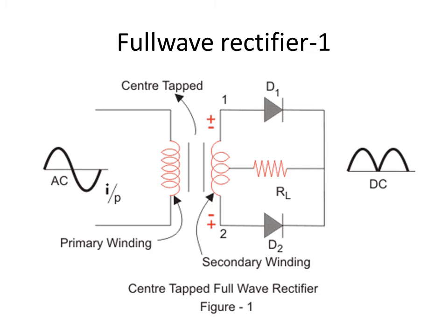Like this, over the end, in between the two end regions of the diode, they will just draw the load resistance, which is wrong, because when the diode D1 is forward biased, it will be conducting current, and that current will be flowing downward through the load resistance if it is connected like that. And during the other cycle, the second diode will be conducting, and then in that case the current will be flowing in the upward direction through the load resistance.